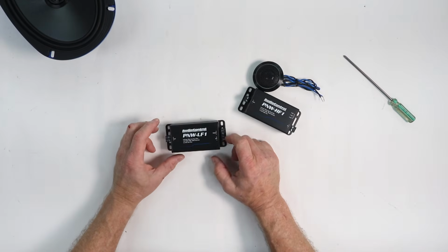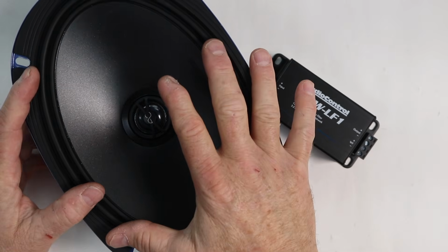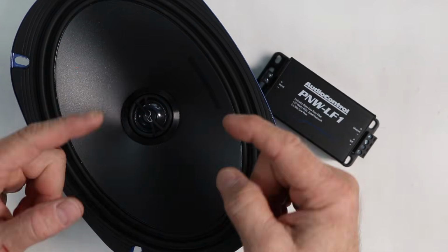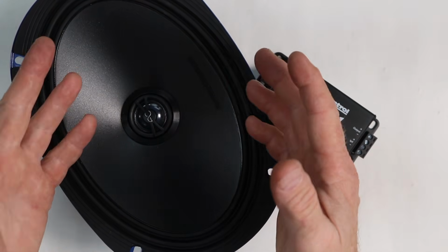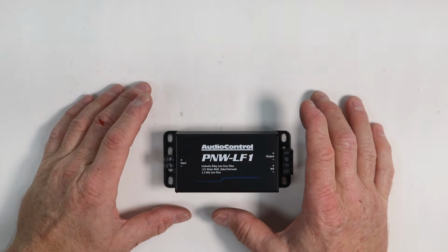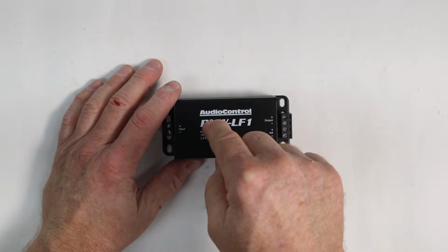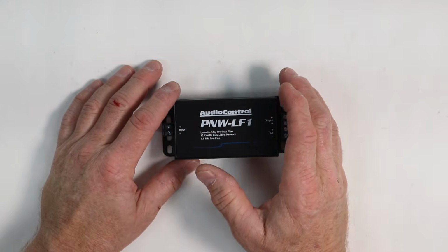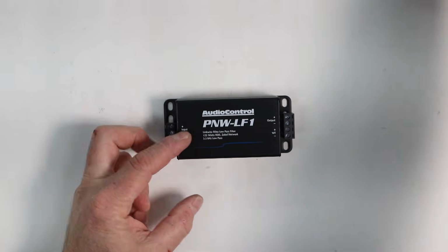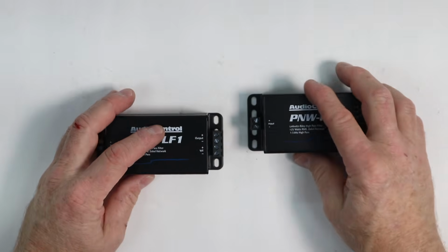Back to the mid-bass, this gave us a lot more potential to make the mid-bass sound better as well. On this style driver, the mid-bass just naturally rolls off. There's really no control with it. It's just designed to blend with the tweeter, and by design you hope you get what you plan for. And this gave us the ability to control the mid-bass a little bit better, because now we could take our cap and coil, or in this case a coil and a cap, make a 12 dB low pass filter so that when the sound was playing it would roll off before it played the same frequencies as the tweeter, creating a low pass and a high pass scenario.